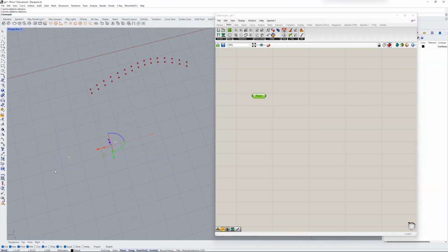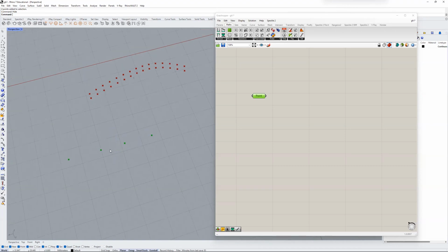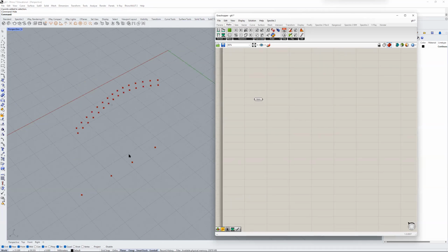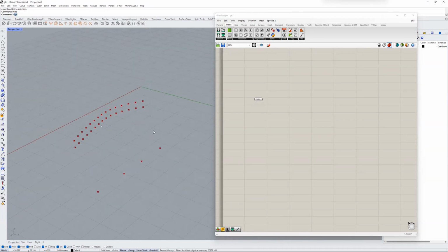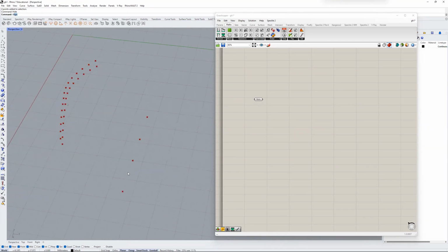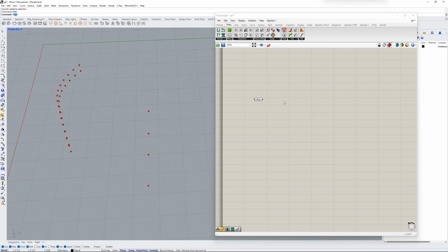And you can hide all of your Rhino stuff now. So if I just select that, hide that, that way I don't accidentally bump it and move it around. So now I have my points. What I want to do is have a way to use sliders and move them along the y-axis. So left to right, if I'm looking at it this way. And I'm going to do that by first searching for the move component. Obviously I want to move points, so that's what I want.